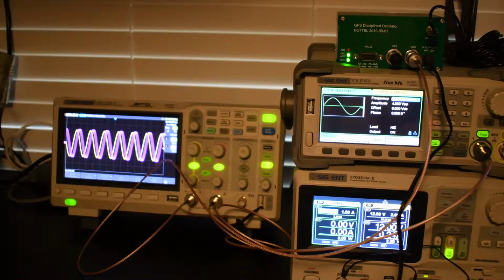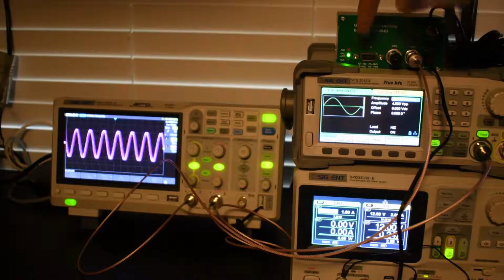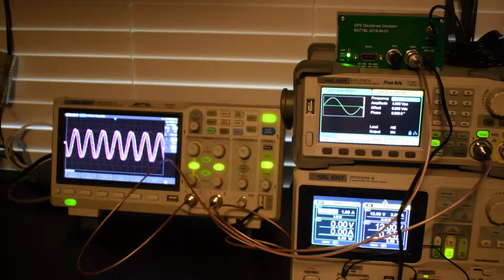So now these two oscillators have pretty well reached steady state, and their frequencies relative to each other haven't changed that much in the last few minutes. So they're both still nominally 10 megahertz. And now the GPS disciplined oscillator has a GPS lock, so that's what this LED in the middle indicates. And so they're still shifting in phase relative to each other, which means that they're not the exact same frequency. And how much the phase difference changes with time is what the frequency difference is. So if you look at the oscilloscope and just see how much the phase changes with time, it's somewhere in the range of maybe 1 to 5 hertz or something like that.